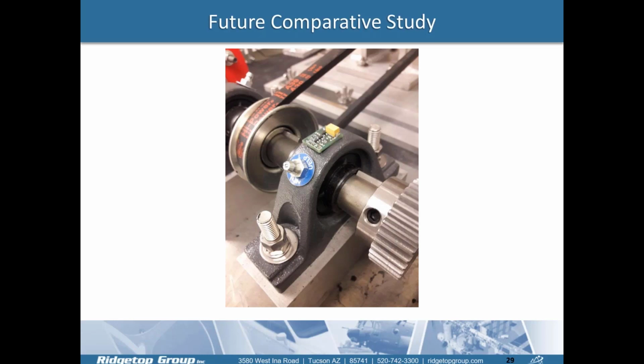But definitely, theoretically, we can say that this signal should be less strong than the transversal signal that we collected on the shaft, due to the fact that the signal collected here went through all the inner and outer races and the rollers, and definitely it should be less strong.